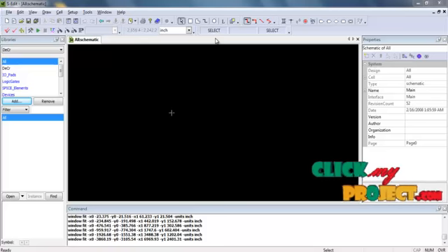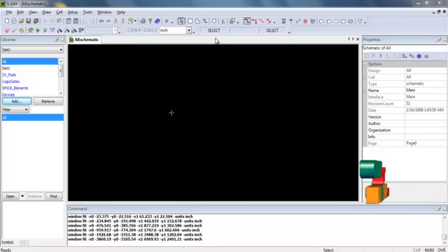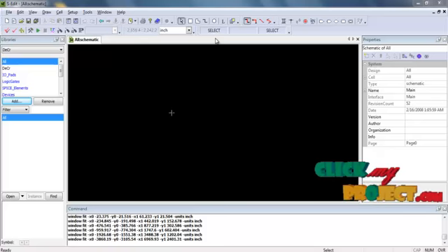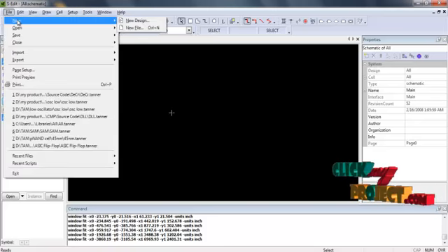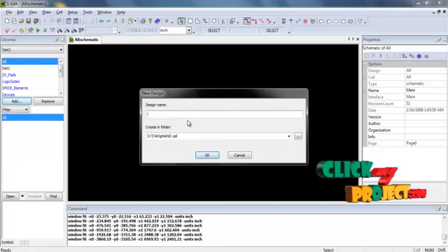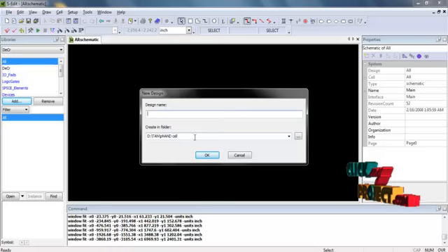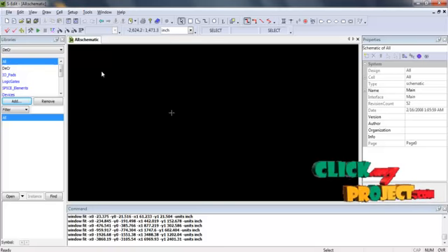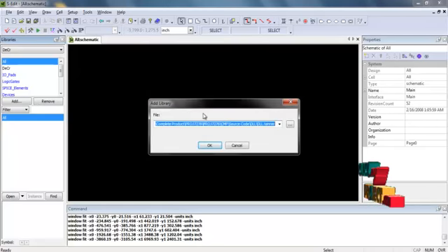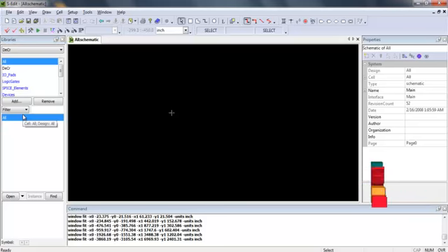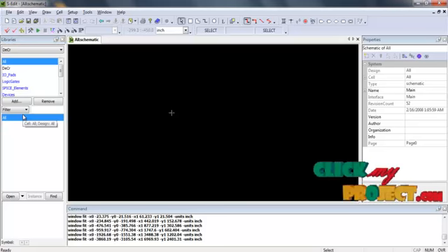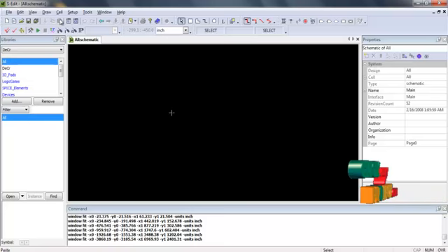Now we are going to discuss the running procedure of our product. Our product can be implemented using the Tanner EDA tool, version 13.0. Now we double click to open the tool window and create a new design using the File menu. File, New Design, to create a new design with the desired name in the desired path. After creating a new design, add the library files from the add option, from the desired path of the library file, and click OK. After adding the library, now we are going to create a new cell to start the simulation design.